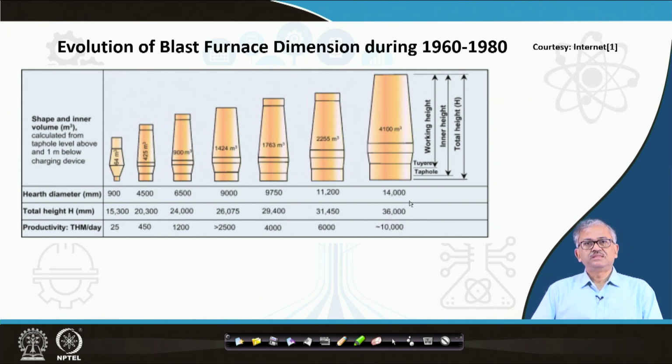And this is because if you increase the height, then the overburden on the blast furnace increases, and all the burden material has to move a longer distance. When the burden moves a longer distance, there is a lot of abrasion, and as a result the chances of fines generation become more, and maintaining the permeability becomes very difficult unless you have a very good burden material. The burden material has already increased its strength, but if you go on increasing the height, that strength may not be sufficient. Eventually, when they come down a longer distance, they will create dust, and bed permeability will be affected significantly.